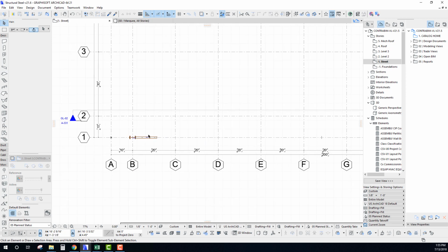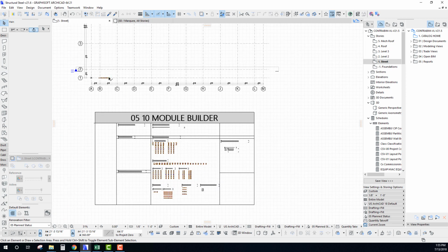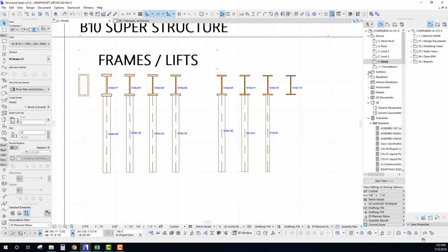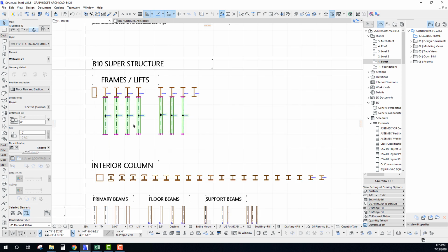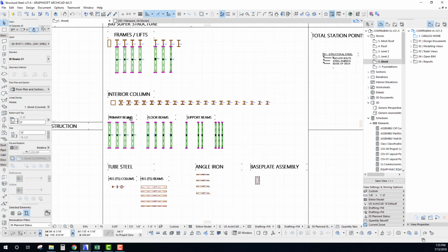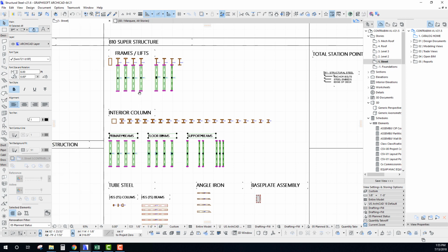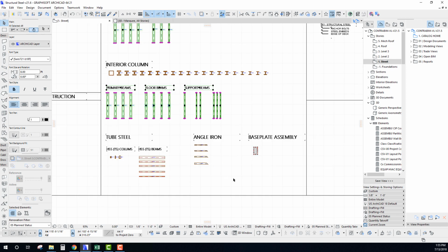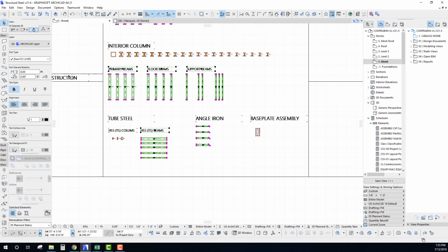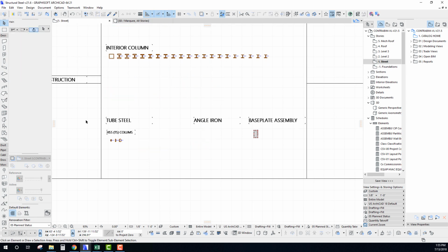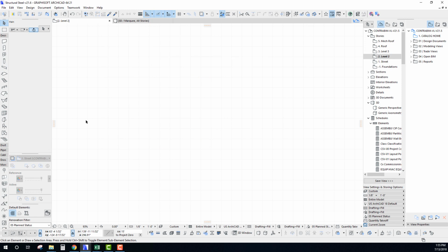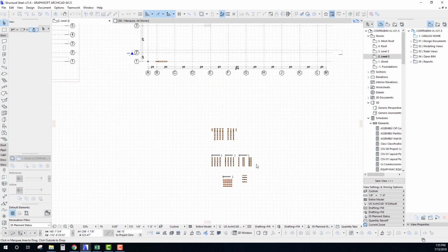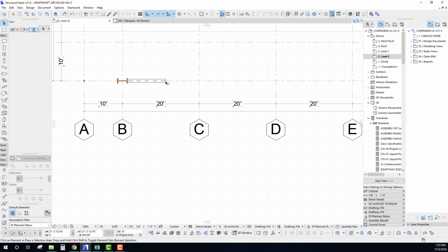And let's go in here, and actually what I want to do is essentially take all the beams here, because we're going to be modeling those on our second floor. I'm going to grab all those beam elements, and we'll grab some of the text there as well, for those at least, and all of these as well. So I'm going to take all of these, cut those, and we'll go up a story and paste them. Okay, so we have our beams now on our second story.